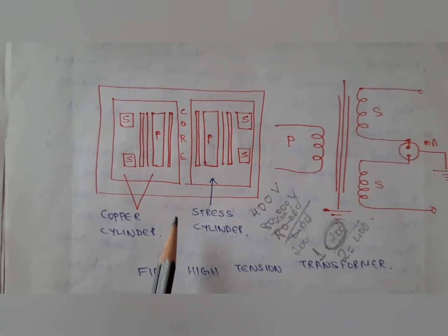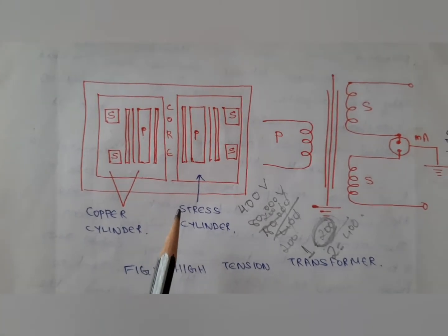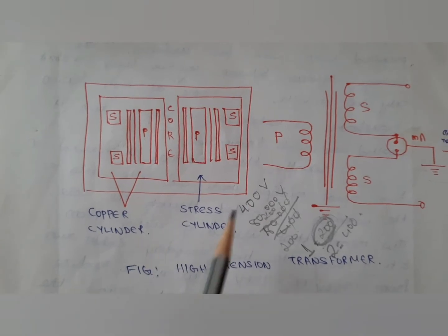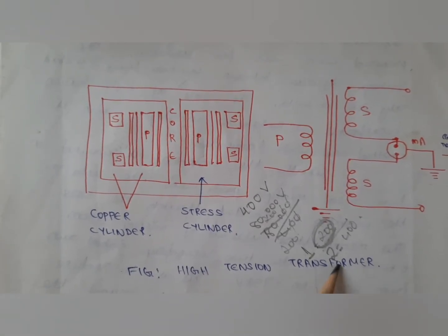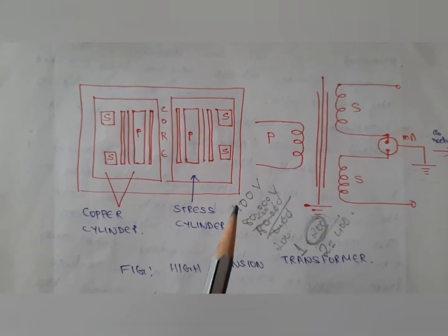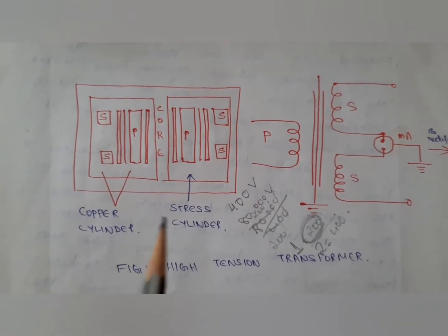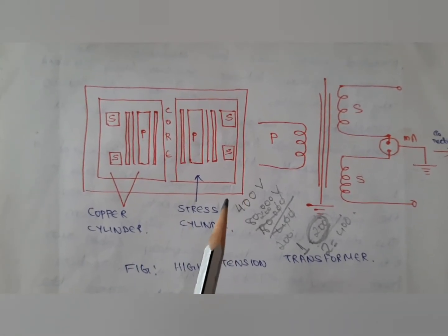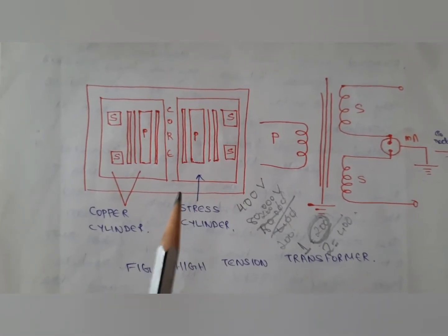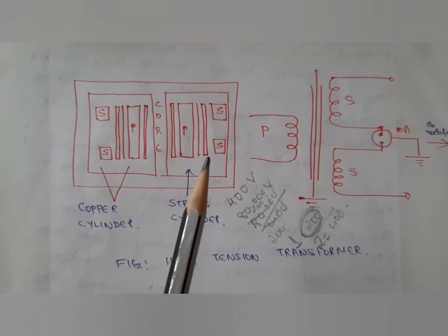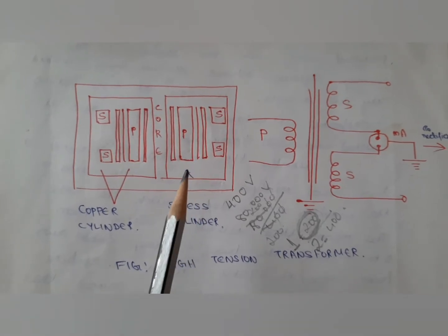Now for the transformers which are used for portable X-ray machines and for dental X-ray equipment, you will not find oil in the high tension transformer, because only a small amount of heat is generated in these equipments. That means in the high tension transformer used for portable and dental X-ray equipment, you will not find insulating oil because the heat generation is comparatively less.